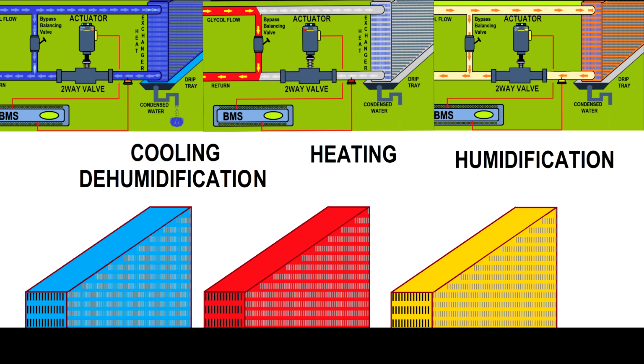On the right hand side, we have to fit a humidifier which will compensate for the humidity we lose in the cooling process. Also, you can see here the heating heat exchanger is not running, only the cooling heat exchanger runs, but at the same time, as a side effect, it will dehumidify the air, and we have to compensate for that by using a humidifier. If you design the system carefully and balance the system properly, you will never have trouble.